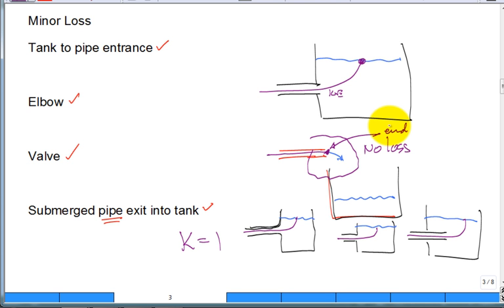Yes? What if the fluid was a gas? Is it zero? No, because you're discharging into the same fluid. So if you're discharging the same fluid, it's really gas into a gas. It's submerged. All that kinetic energy is going to be dissipated. What you'd have to do is, if your pipe is like this and you're discharging into a tank of air, you're going to take your Bernoulli and end it out here somewhere where the air is at rest. And so when you come across, all that's going to be dissipated. Put a loss coefficient of 1. Or I don't see it being a big difference if you maybe end it right there in air.